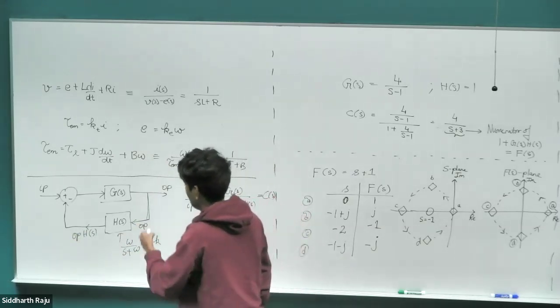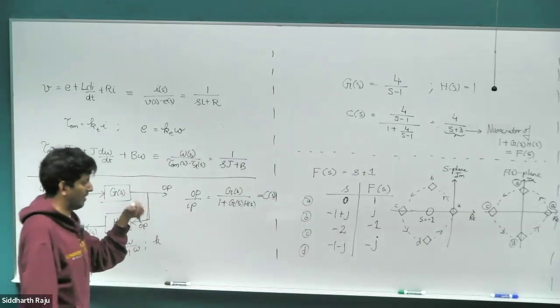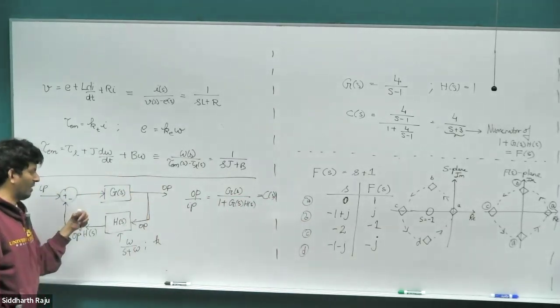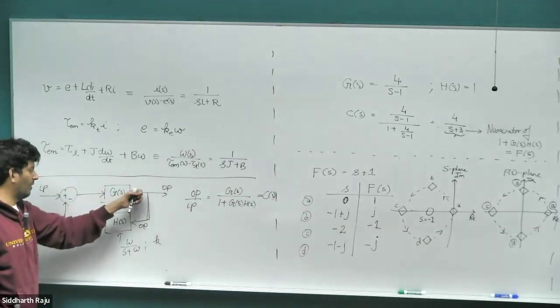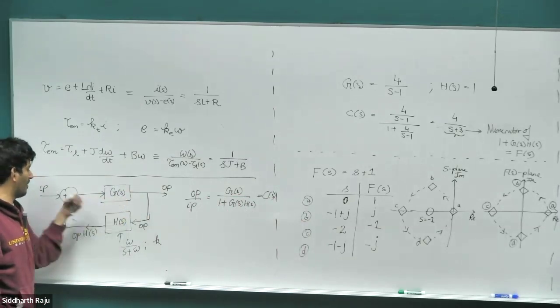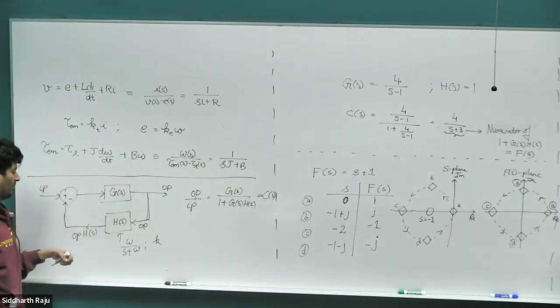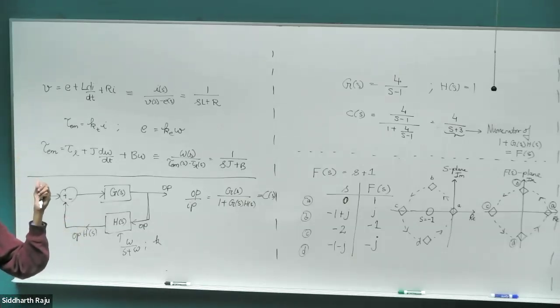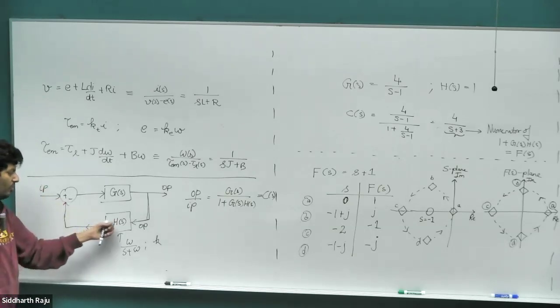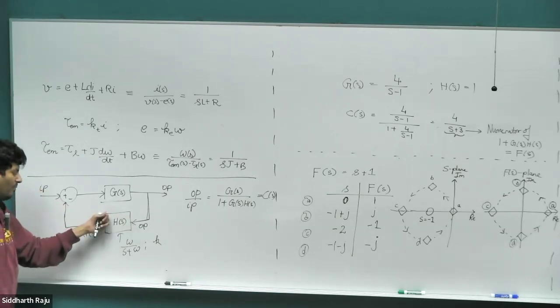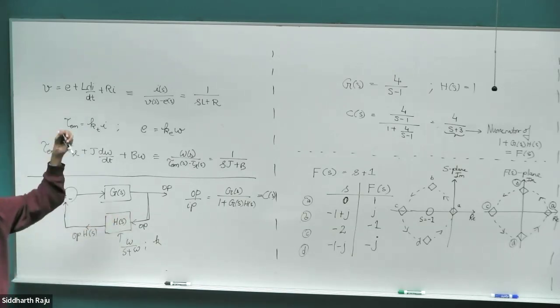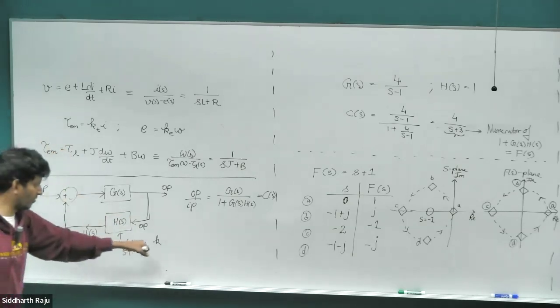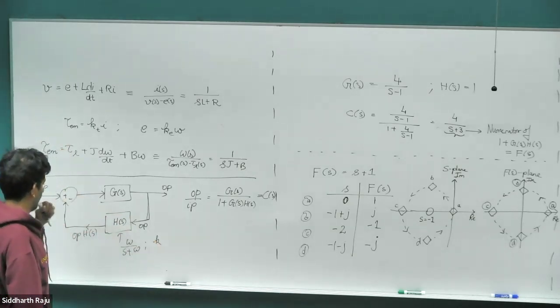So you might be sensing some current, and your current sensor might have attenuated the signal. It might have some gain value associated with it, and you might want to scale that value back up to the original current that you're passing through the system. Or if you're measuring voltage, one typical way is to use a resistor divider circuit. If you're measuring a 100 volt signal, your controller can't process a 100 volt signal, so you would reduce it to, say, 3.3 volts and then measure that value. And then this H of S is basically scaling it back to the original value. So that's what it's doing: any kind of signal feedback processing.